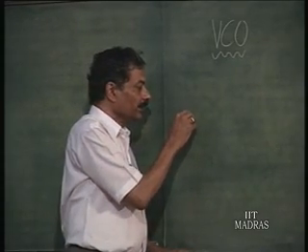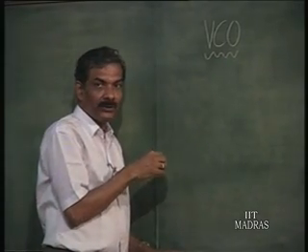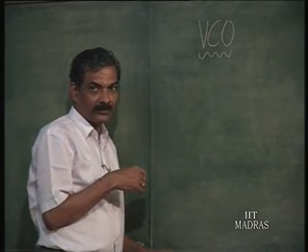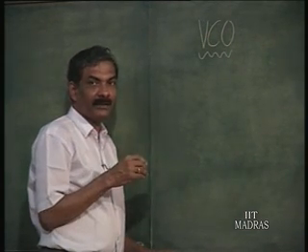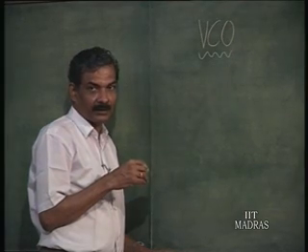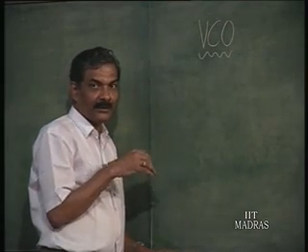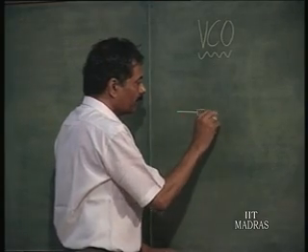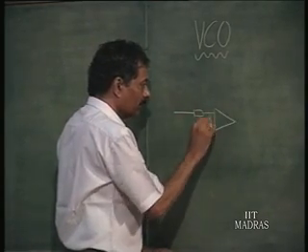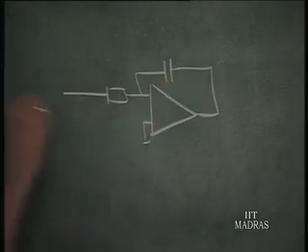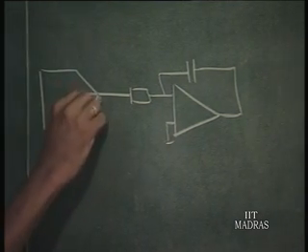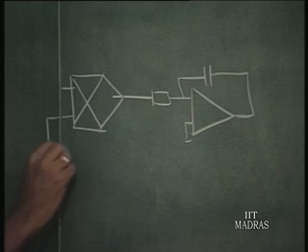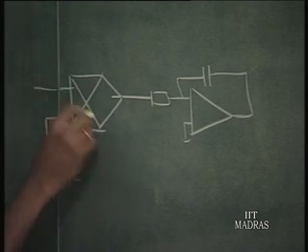What is done is you use an integrator along with a Schmitt trigger. This we had already discussed, we discussed astable multivibrator, use of Schmitt trigger in generating waveforms. So, what we can do is put an integrator and then let this integrator have a multiplier, so that the time constant of the integrator is again controlled by the multiplier.